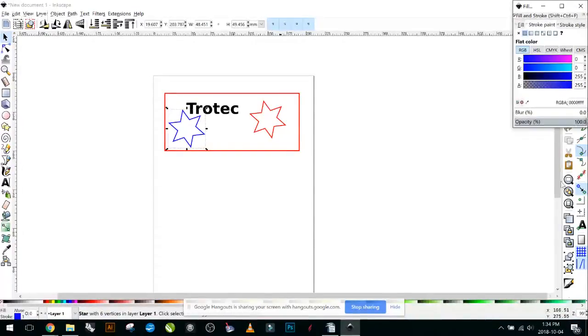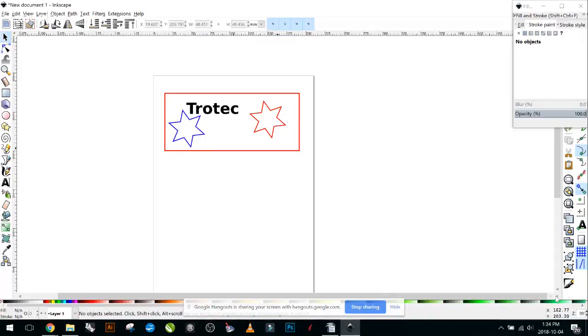We're going to program the laser so when it sees a blue line, it's going to cut, but at a very low power. So instead of cutting right through our material, it's just going to kiss the surface of the material and leave a very faint mark on it. Why we do that is when we cut out our star and it falls out of our material, we want to place it somewhere in a perfect position. So using our kiss cut, we have our faint lines, so we know exactly where to place our freshly cut out star here.